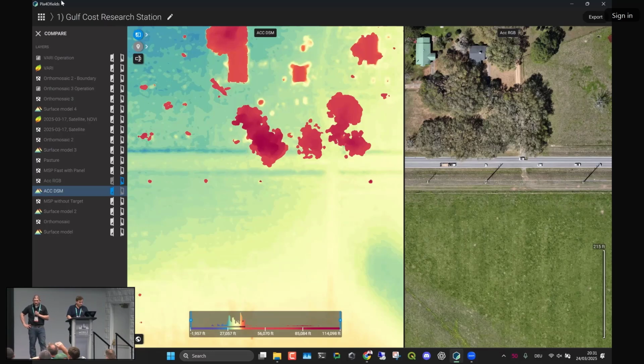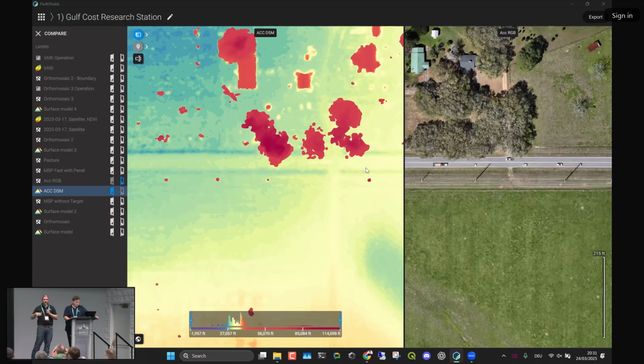Good question. Also, I would say with large areas of elevation, and I'm talking kind of mountains, and we're talking about vineyard applications and things like that. Some of you in here are in California avocado type territory. We have some pretty significant elevation differences. Accurate might be the only one you want to run, because you want to have really good accuracy. Fast is going to work very well in flat territory. But if you're trying to do something with heavy terrain, you may want to do accurate processing.